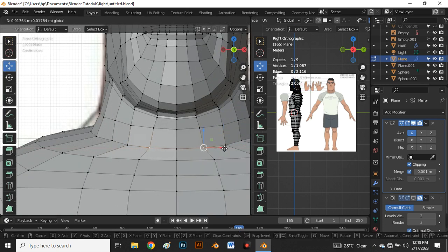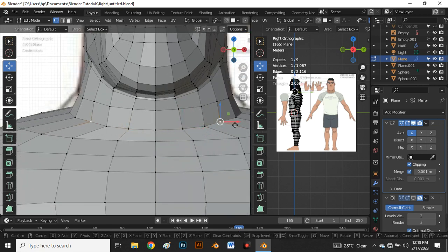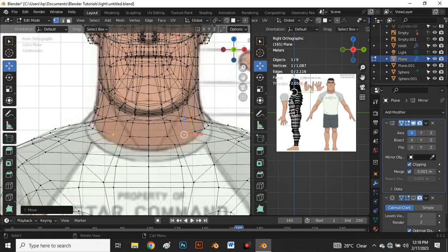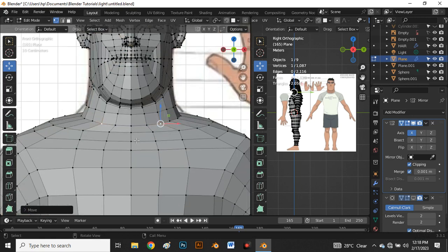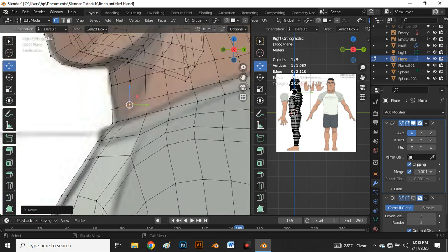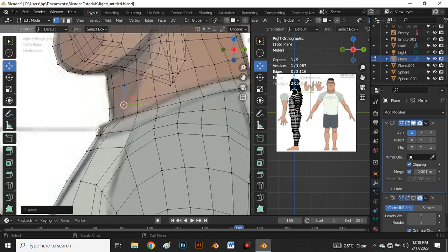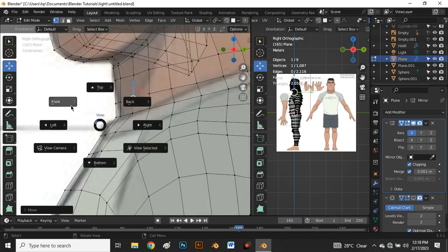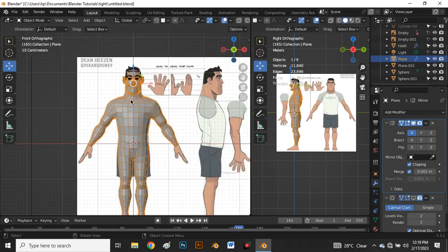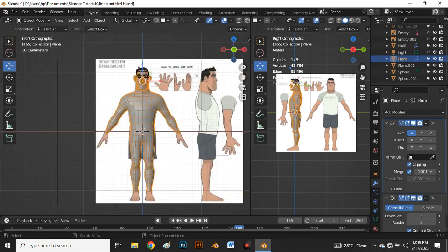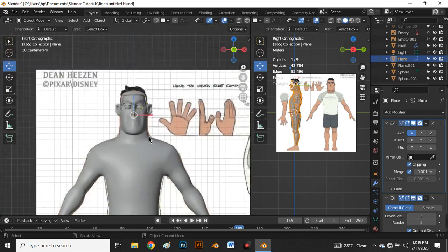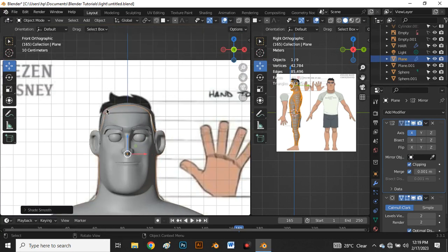Select this. And expand. Alt Z again. Now come to our right view and see if we can make any changes. This is okay now. Now say Tab, so we are done with that. We can turn on our subdivision surface modifier, and now we can turn off our wireframe. So we're going to right click and say shade smooth.